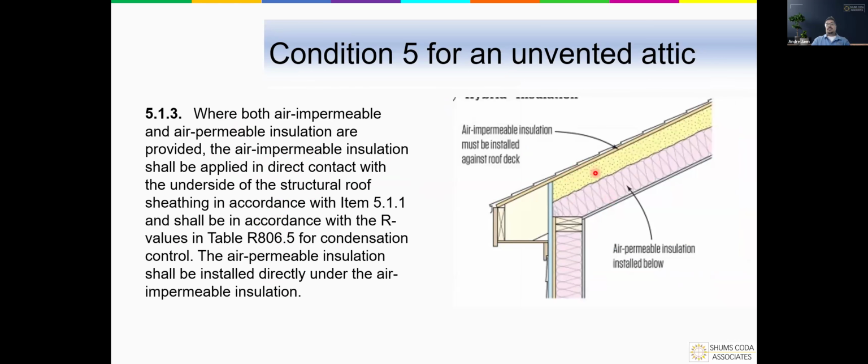And here we have a mixed system of spray foam insulation, and then sometimes the spray foam insulation is really the total insulation needed. We also may need an ignition barrier in order to protect that insulation. For that, we go to Chapter 3 of your IRC, so that way we can look at specifically the requirements associated with those foam plastics. Again, we look at that condensation control related issue.